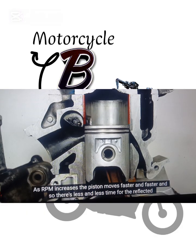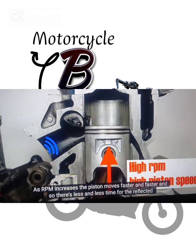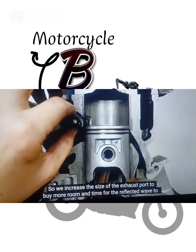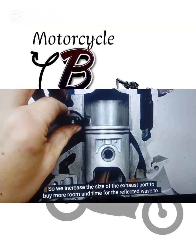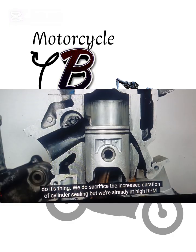As RPM increase, the piston moves faster and faster, and so there's less and less time for the reflected wave from the expansion chamber to make it back to the cylinder and push the air and fuel back in. So we increase the size of the exhaust port to buy more room and time for the reflected wave to do its thing. We do sacrifice the increased duration of cylinder sealing, but we're already at high RPM, so building power and torque really isn't an issue at this point.